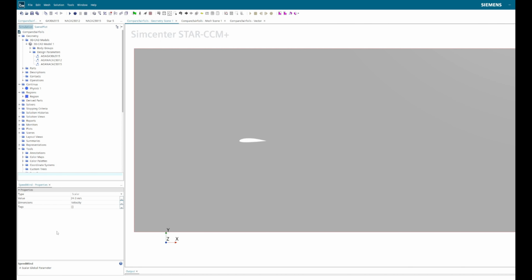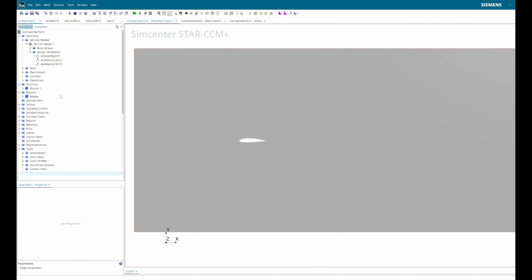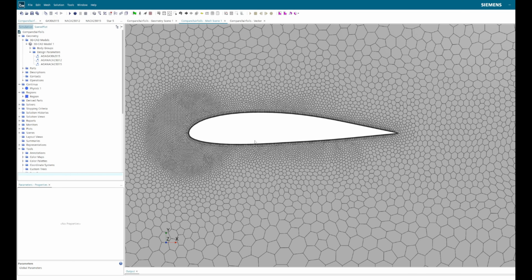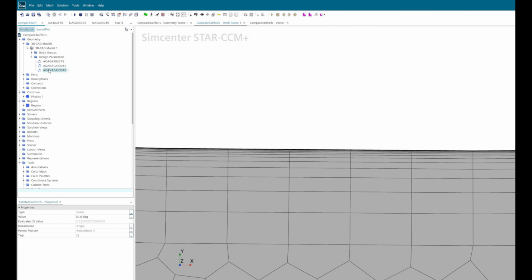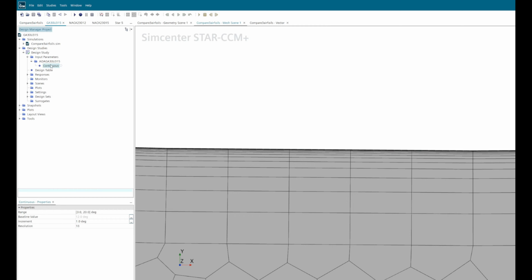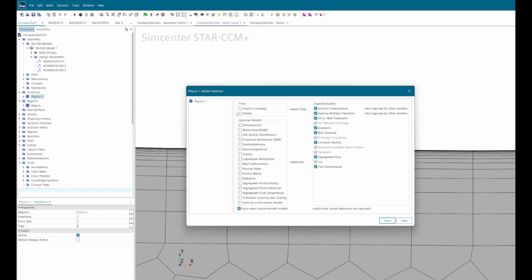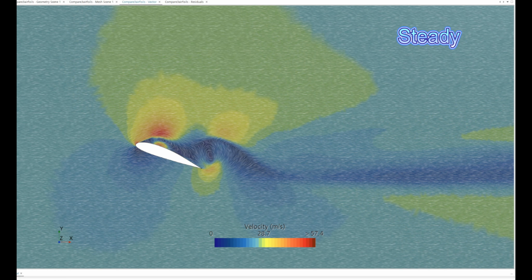First, let me briefly explain the test environment. All three airfoil tests use the same incoming flow conditions, with V equals 30 meters per second. A consistent meshing method is applied. The calculations are performed by varying the angle of attack under the same setup. In the computation, a two-dimensional incompressible external flow, RANS, is considered with the SST k-omega turbulence model.